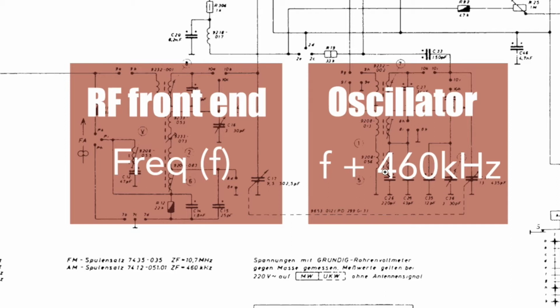And then, because you've adjusted this tank circuit, you then adjust that tank circuit so that the strength of the signal that you're hearing at that point is optimized, as strong as possible. So you filtered the front end to match the frequency you're tuning to by moving around the oscillator frequency. Okay? So you basically have these two frequencies that you're tuning in conjunction with what you're seeing on the dial of the radio. And this signal, the front end, obviously comes from the antenna, which is off to the left there. And that's basically what you're doing when you're adjusting the front end of the radio.